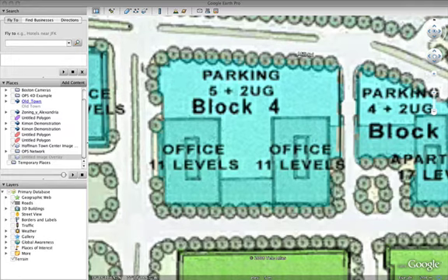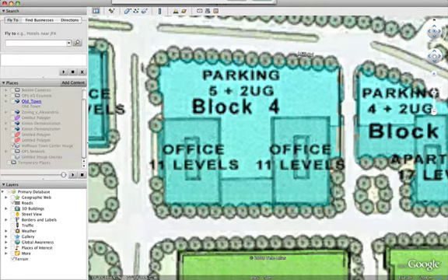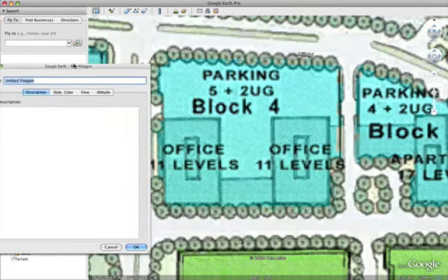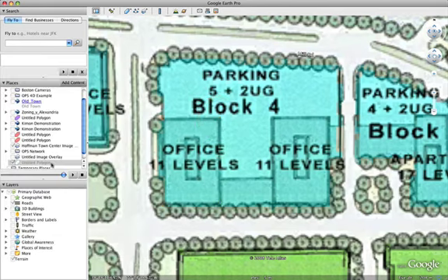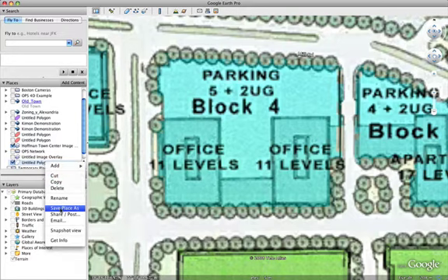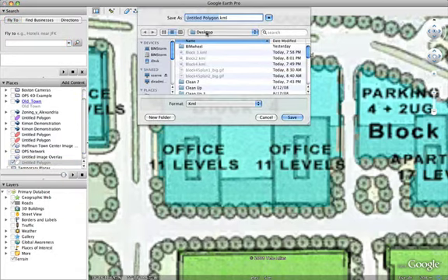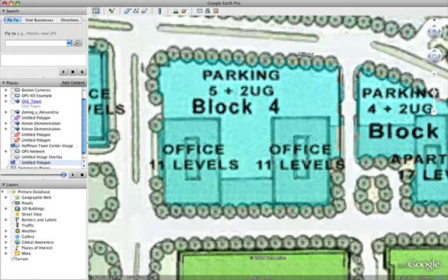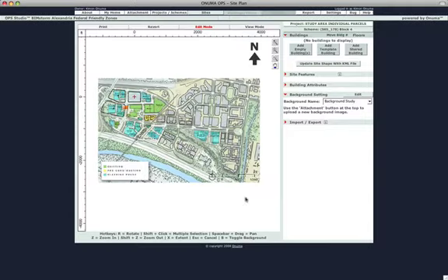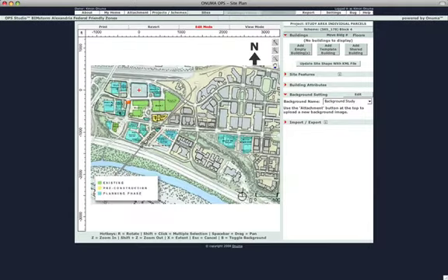We're going to go back to Google Earth now and save an outline of a building in the same way that we saved a property line. Using the polygon tool, I'm going to click on the 4 corners of this office building and save that. And then right click and save that as a KML file. And jump back into OPS. Same plan we were looking at earlier.